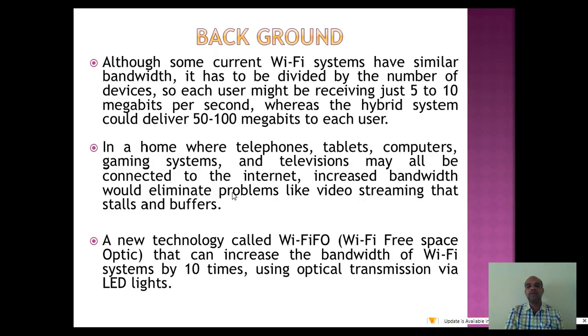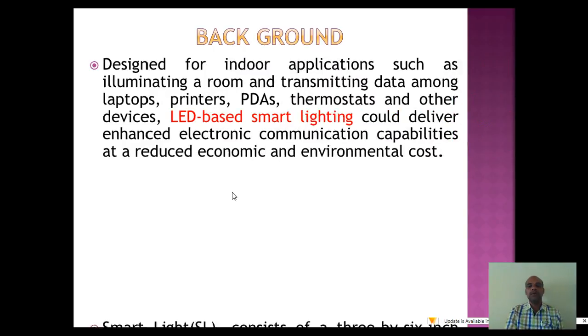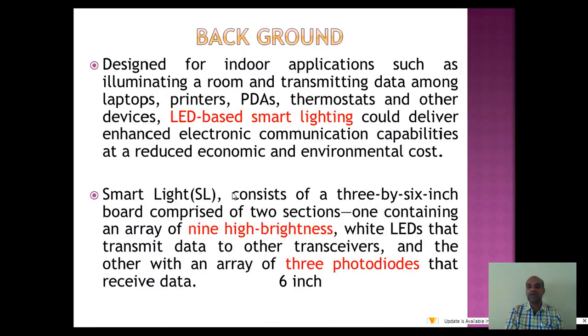Another technology, Wi-Fi free space optic, can increase the bandwidth of Wi-Fi systems by 10 times using optical transmission with the help of LED lights. This is mainly designed for indoor applications. Why? Because indoors the light can be transmitted easily. In the case of outdoors, there may be interruptions from sunlight or other external devices.